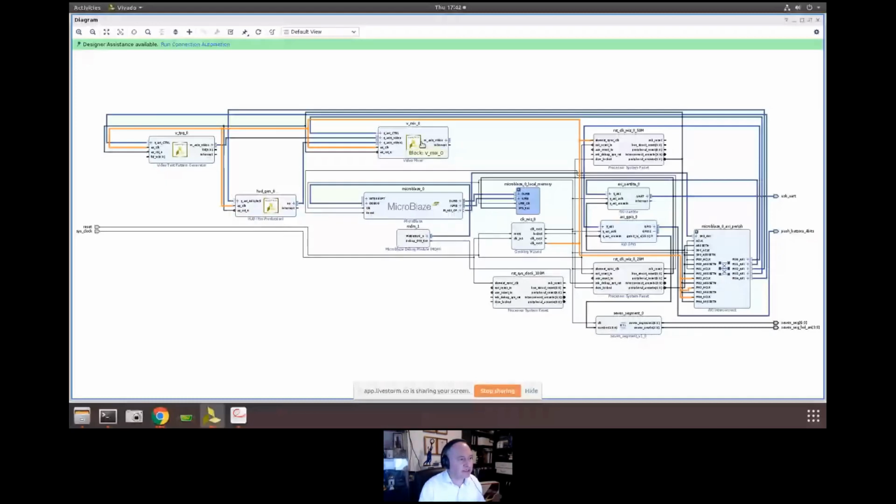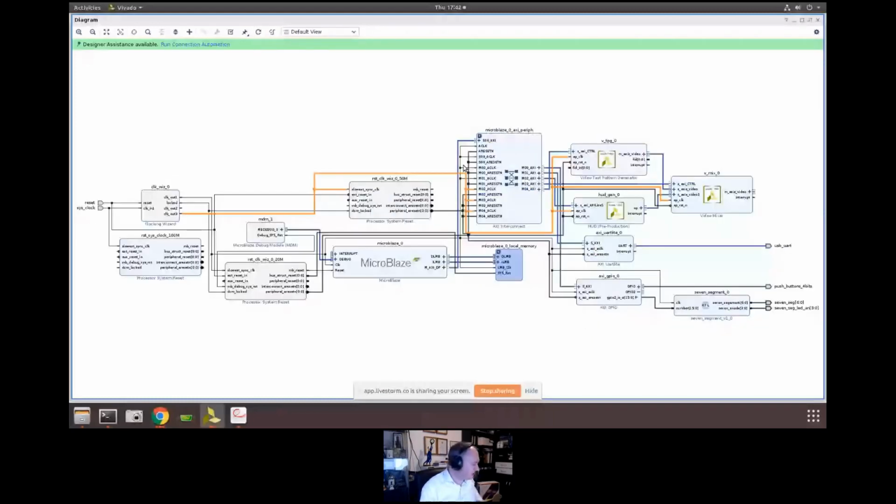So everything's all nicely done there in our design. And you can see the AXI peripheral as well down here. That's actually pulled it through and has got everything all connected. So it will do all the clock domain crossing, and everything that we're going to do will be included as part of that. So I'm just going to regenerate my layout a little bit, just so as we can see it a little bit better.